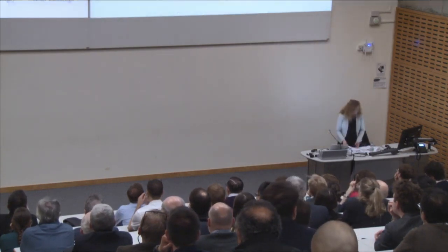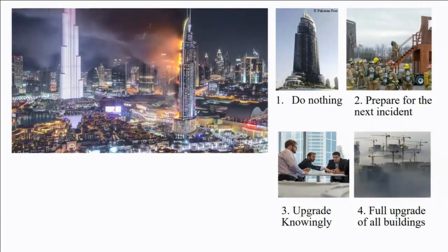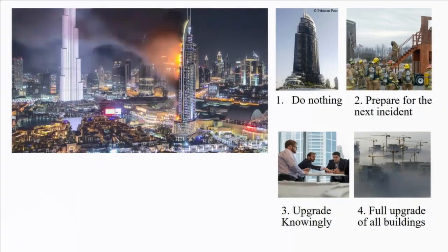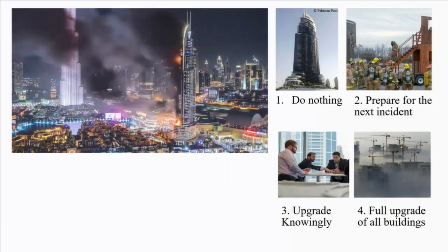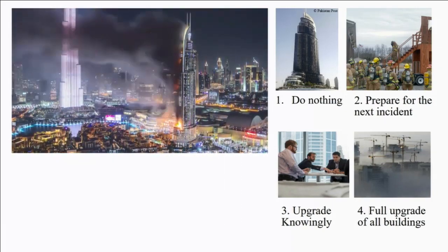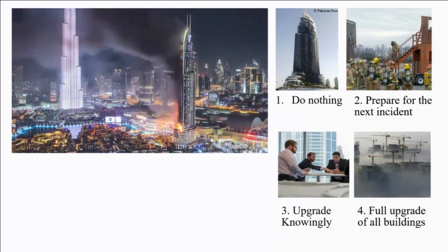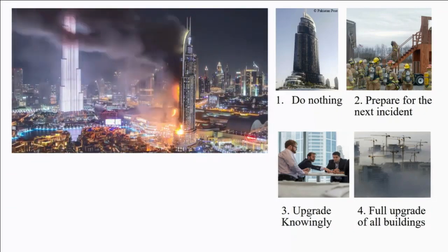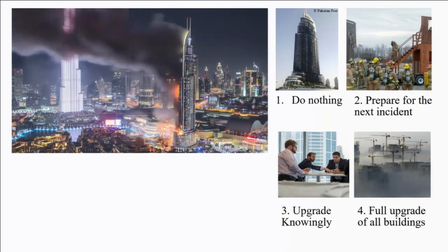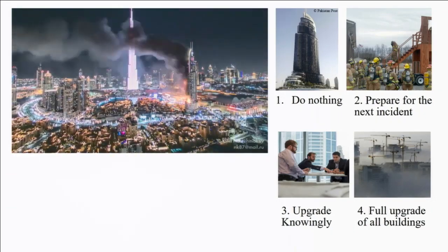Then another notable fire at the Address Downtown Hotel near the centre of Dubai, New Year's Eve 2015. This time the fire started on a 20th floor terrace of a 63-storey hotel. About 1/4 of the facade was consumed by the fire. The fire spread in all directions, and this was ACP cladding.